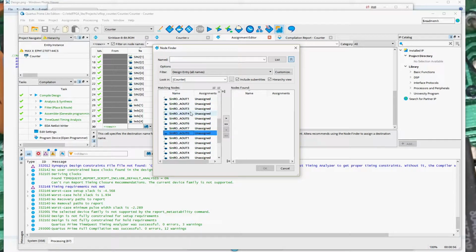I'm trying to interpret what I'm seeing here. These being named A out 1, 2, 3, 4, 5, 6, 7, A out 0. Why does that name look identical to that name? It's just maybe the way the Verilog is defined. Anyhow, I expected to have to connect to the ROM, hook up the incoming address pins, hook up the data outs, enable the ROM through the enable pins, etc. And I didn't have to do any of that.